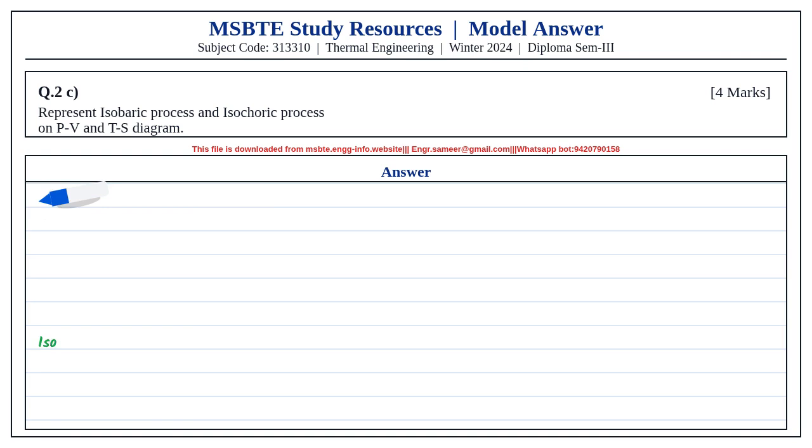Question 3D. Give classification of boiler. Boilers are classified as follows. According to contents in tube, they are fire tube boiler and water tube boiler. According to circulation, they are natural circulation and forced circulation boilers. According to position of furnace, they are internally fired and externally fired boilers.